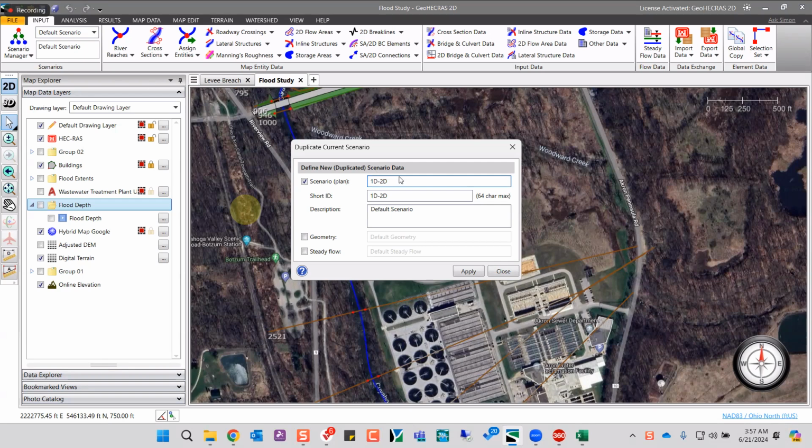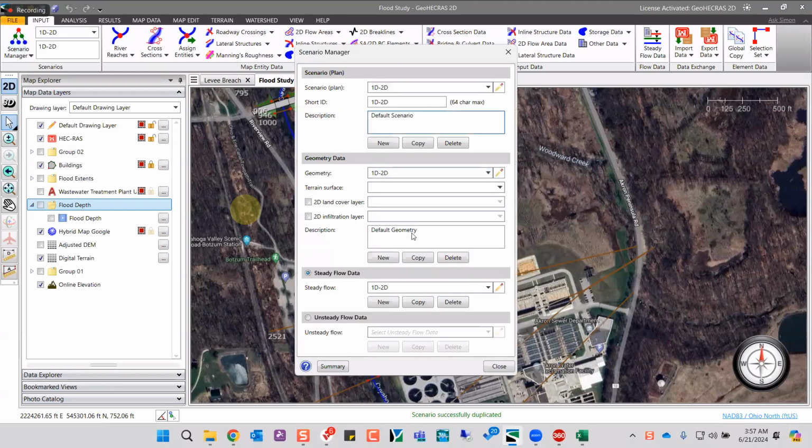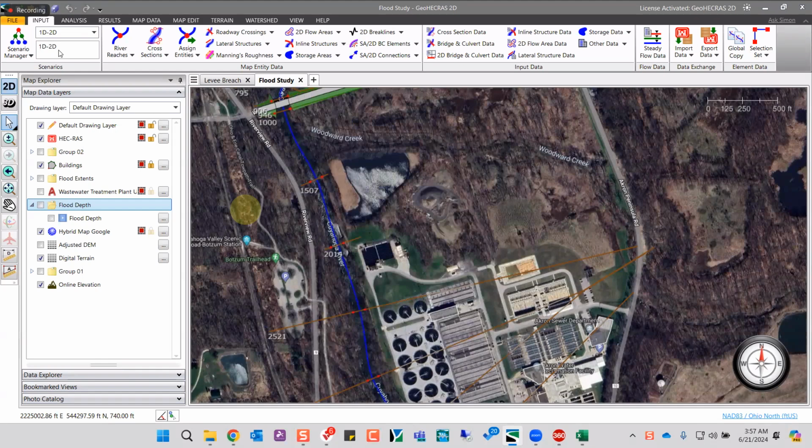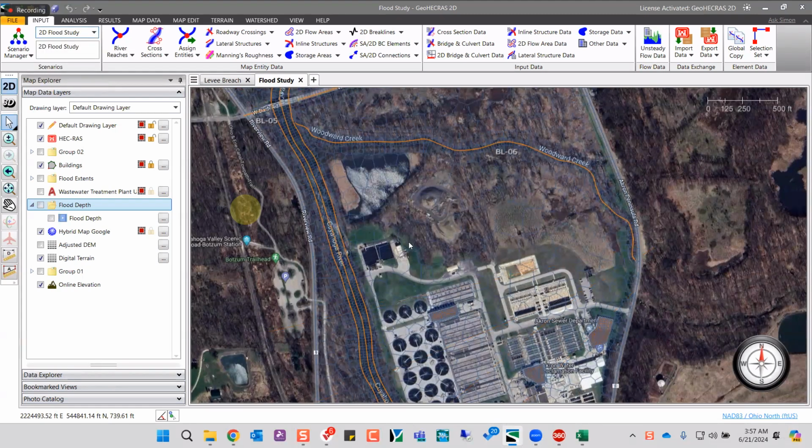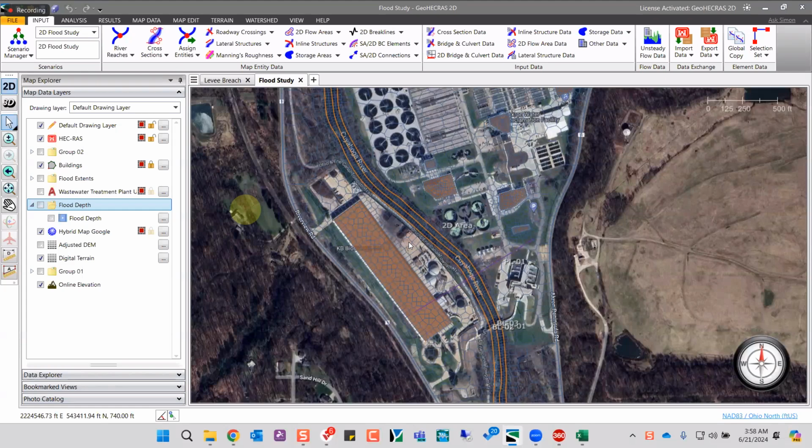Okay, for the first simulation, I saw that the water was moving over the buildings. So how do you know that this is not the case of submergence? For example, if the buildings are short, the water can submerge the buildings. In this case, these buildings had higher elevation, so the water did not cross it. In case your water surface elevation goes higher, your buildings would be submerged.